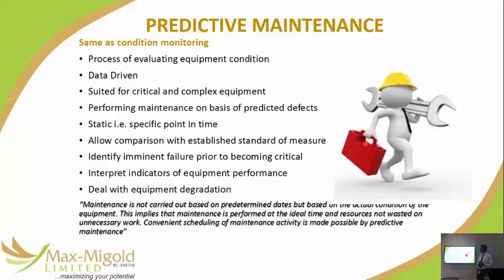Okay. Comparison: static, specific point in time, means you have a set of logs. The logs are recording certain things as part of the operation. Take what's the most common one? Generators. It was bought, commissioned, everything is working fine. You have a log that says every day by 6 a.m. take the temperature, take the oil pressure, take the water level, take the kilowatt reading, take the hour run. You're recording those regularly. Take the same, the vibration level. All of those have been recorded